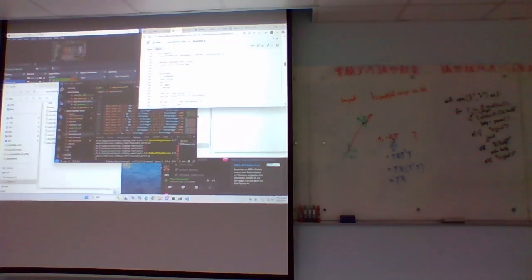So forward kinematics, then here is calculating the Jacobian, which simply goes through each joint and changes it by a little bit, calculates the forward kinematics, gets the position, looks at the difference between those two, and divides it by some kind of step size.